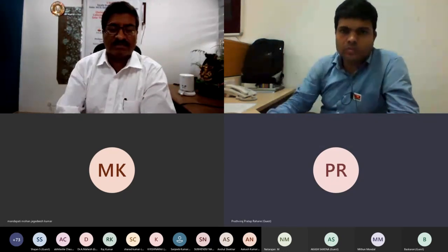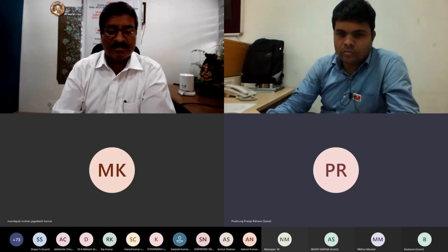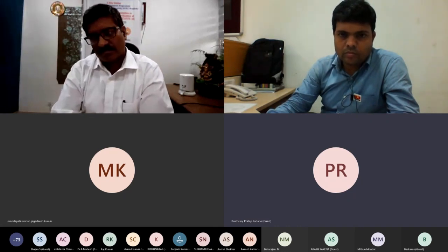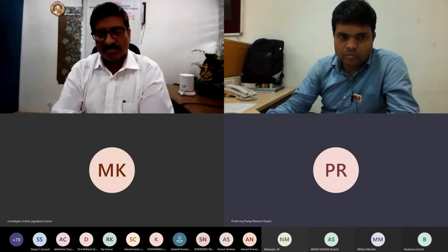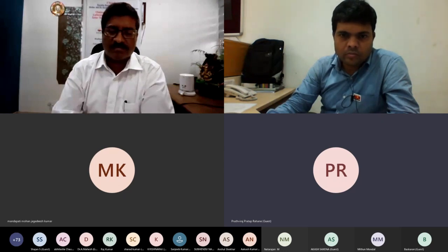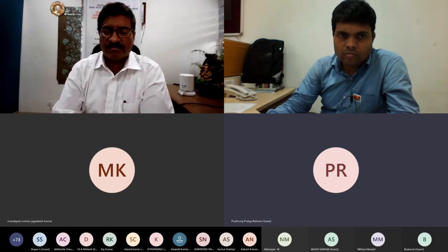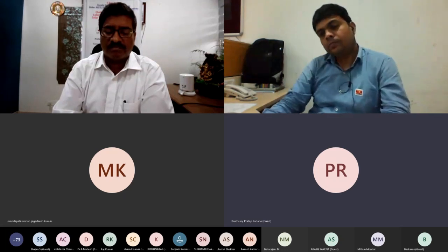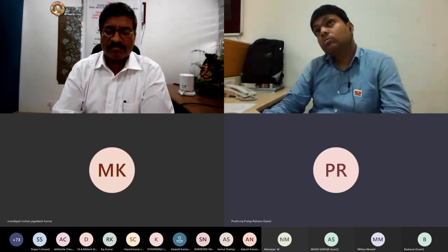I want to ask one question regarding pyranometers. In the market, generally two types are available: one is the silicon type and one is the thermopile type. The sensitivity and accuracy of the silicon and thermopile pyranometers are a bit different, and they are costly also, because the thermopile range will vary from 0 to 3000 or more watt per meter square.